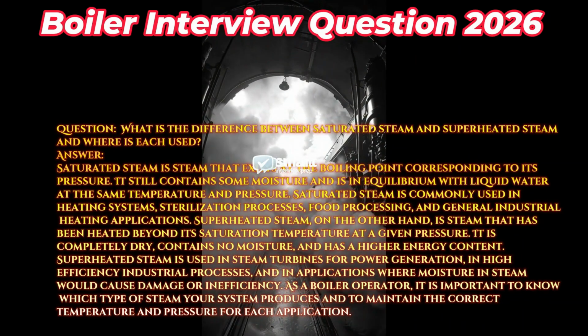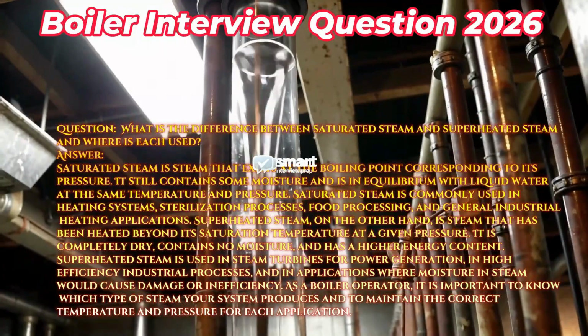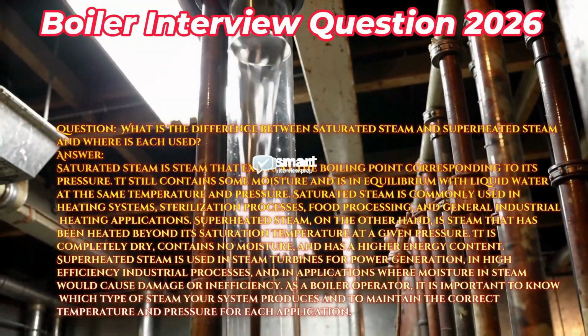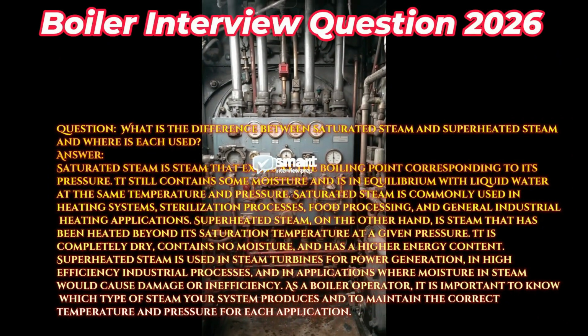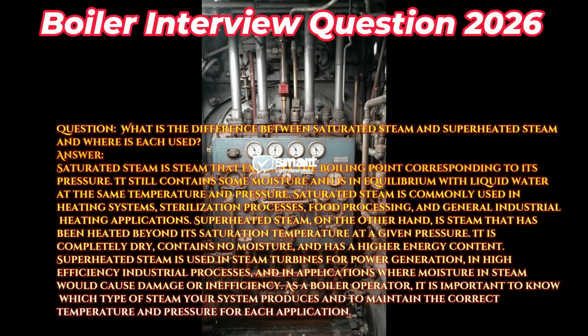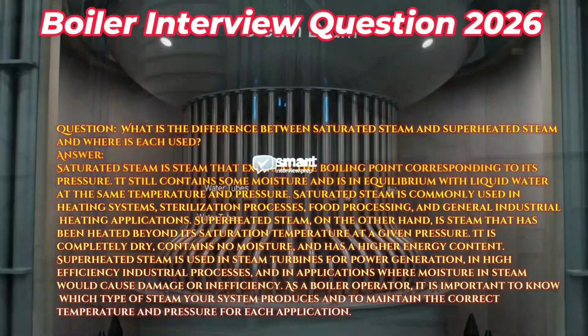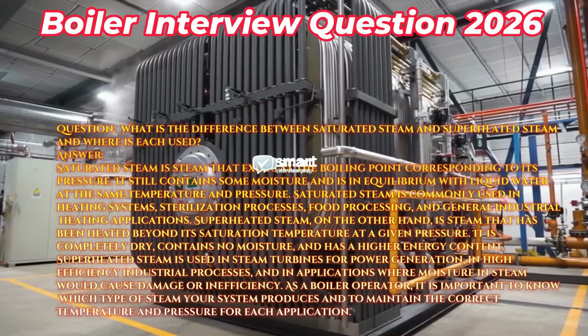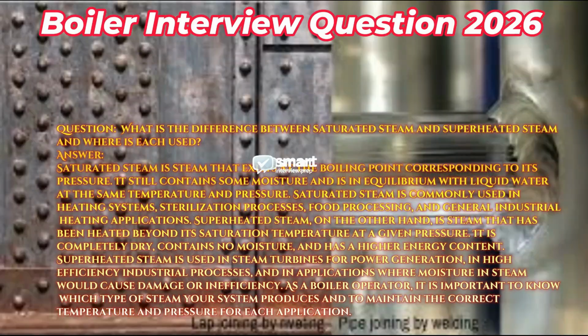Question: what is the difference between saturated steam and superheated steam, and where is each used? Answer: saturated steam is steam that exists at the boiling point corresponding to its pressure. It still contains some moisture and is in equilibrium with liquid water at the same temperature and pressure. Saturated steam is commonly used in heating systems, sterilization processes, food processing, and general industrial heating applications.